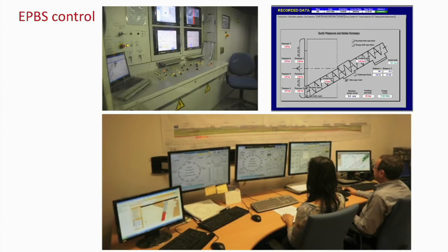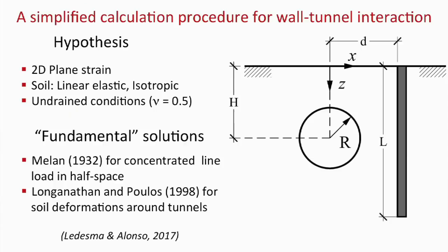So you have a number of things that you can do. Most of them are pressures that you apply. Pressures that you apply on the front part, you can measure the weight of the soil being extracted, and also the pressures across through the shield, and also in the back part. You remember the P3, etc. And well, there was an office doing that, as I said, in real time.